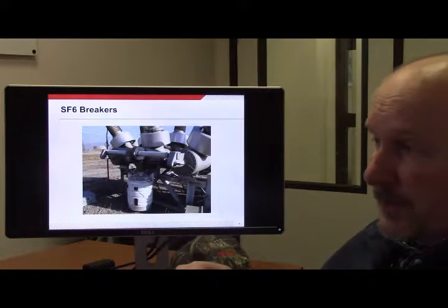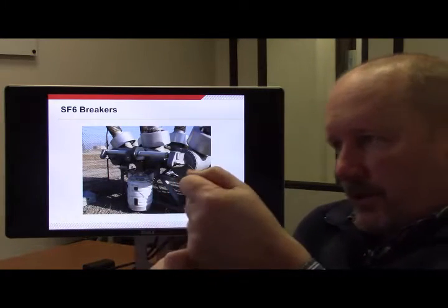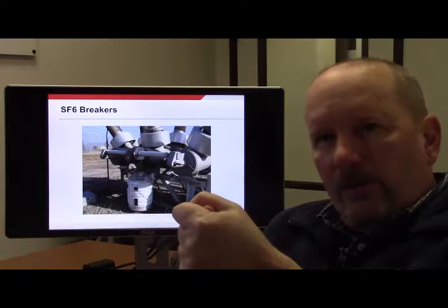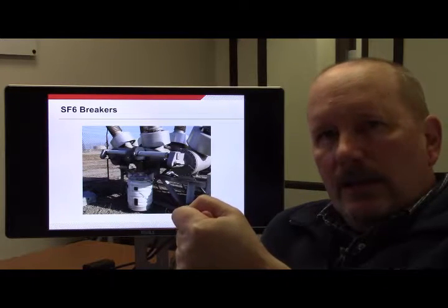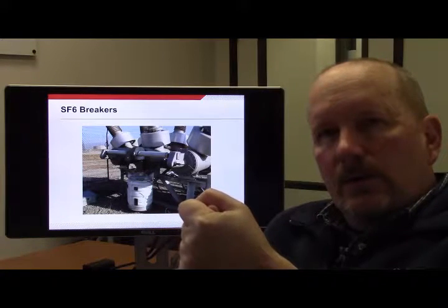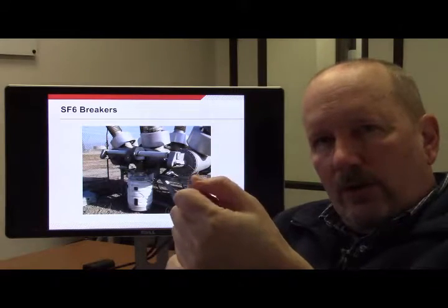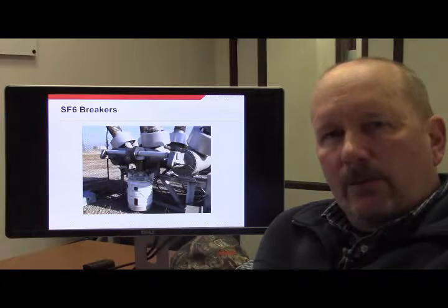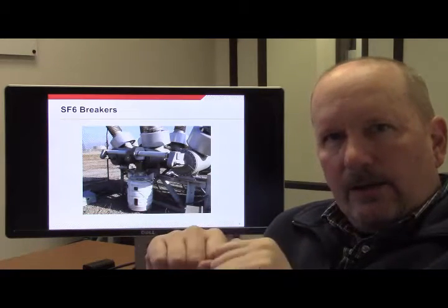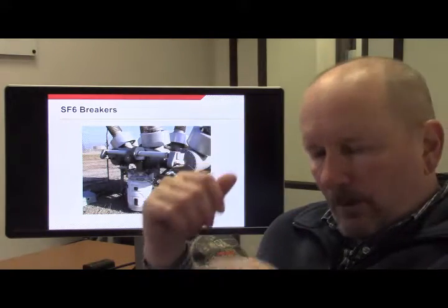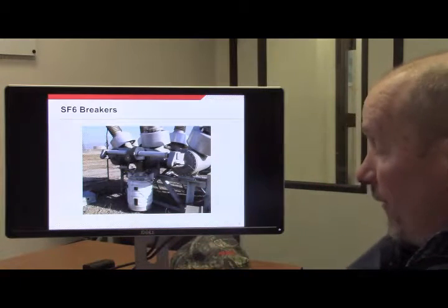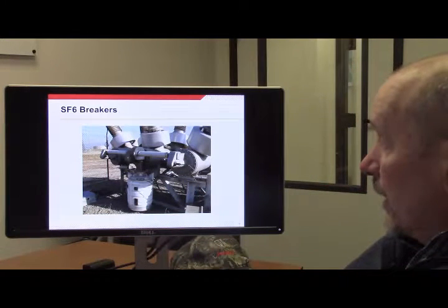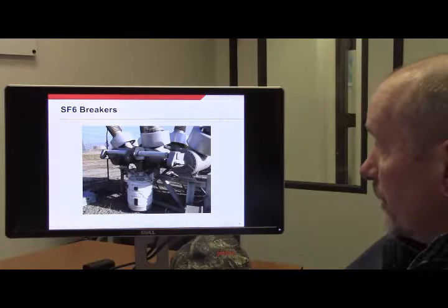And what actually happens is there's a little plunger that goes through a solenoid, and when you trip the trip coil, you run current through that solenoid, and it pulls that little plunger up, and it then releases the mechanism, and it twists and opens your circuit breaker. Anyway, a fascinating device, and I'm sure through the course of your career you'll become very familiar with this thing.